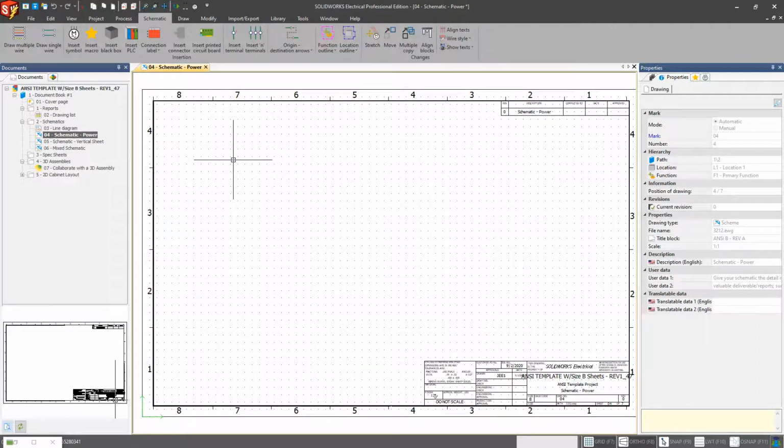I have many examples of bill of materials where, perfect example, the company that I work with has two different bill of materials. One is for the logistics team who needs to order everything. And then one bill of materials is for the folks on the shop floor, where they don't necessarily need to know what vendor you bought everything from. So with just a click of the mouse, you can generate almost the same report, but one has certain information, one doesn't. And it's all generated automatically based off of everything you have in your schematic. So I'll say it again, garbage in, garbage out. The more information you put into your schematic, the better your reports are going to be on the back end.